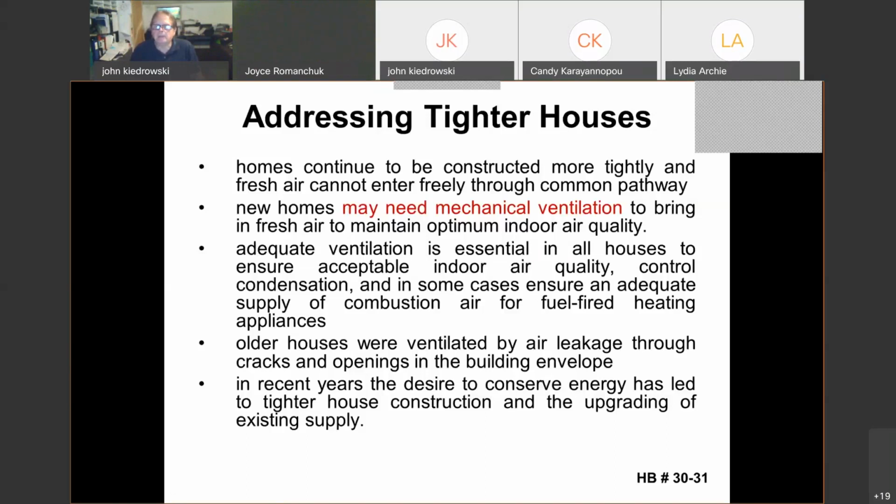So something like the heat recovery ventilation system. When we take a look at that, it's going to exhaust the stale air out, which is heated. It's going to bring fresh and even in the winter colder air in. But when the two merge in the HRV box, they basically exchange the heat that'll help temper that colder air coming into the house. So it's not extremely cold, but certainly cold air that can be tempered by the exhausted air going out. So it's a very good, efficient system. By the way, not very cheap though either.